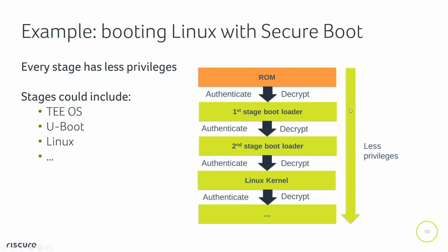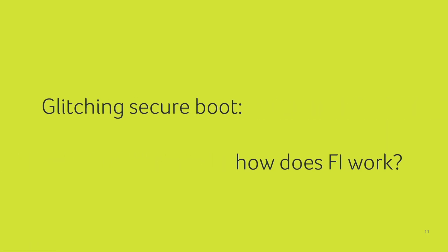And something that also is very common is that the moment you start jumping to the next bootloader stage, you also limit what is possible on the system. The next stage bootloaders have fewer privileges. So if your applications get compromised, they may not be able to, for example, overwrite the first stage bootloaders. So we have talked about the beauty of secure boot. It's a very elegant and simple design, but it's very powerful. This has saved many systems from a full system compromise because it can restore the code to a trusted scenario.